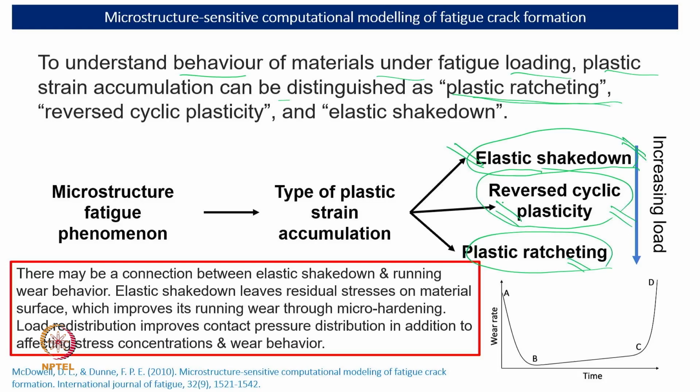However, I just want to connect this with the mechanism which we have studied, something like a bathtub curve. You know this is the complete bathtub curve. We know that from A to B, or B to A, is where it is maximum. Now, why is it happening here? At level A, the few asperities that come into contact have a very high stress level. Now, with sliding, the asperities change shape. Initially very sharp peaks become slightly plastic, and under plastic deformation they get some sort of contour at the bottom. Because of the contour, the projection angle or cone angle will increase in size. That is why the stress is coming down.